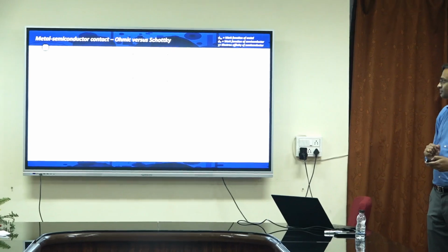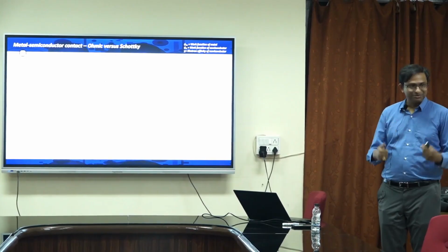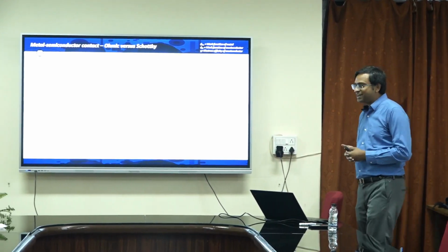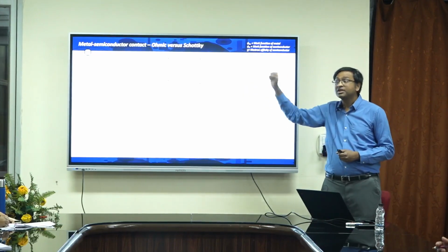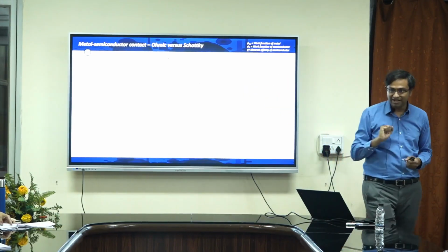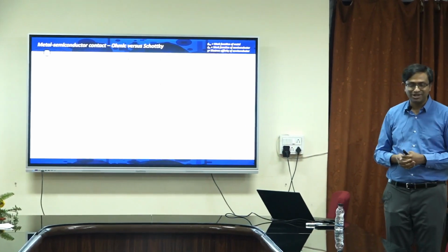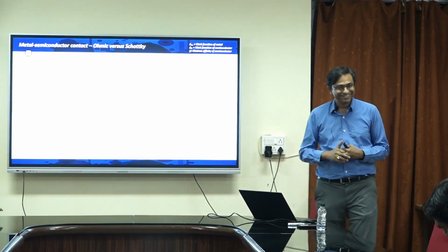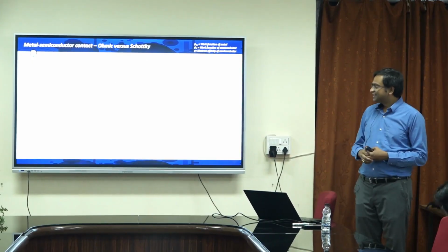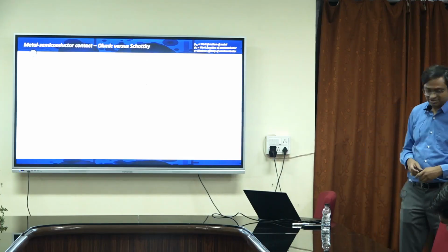Another task. We will have practice. So what about the band diagram for this? Now you see what the material is here: the semiconductor is P type, because the Fermi level is close to the valence band. Now let's try it one more time. By the end of the day today, you will be experts in drawing band diagrams. That is one thing you will definitely learn out of this GaN course. Same rules. It doesn't matter whether it is N or P, the basic rules are the same.